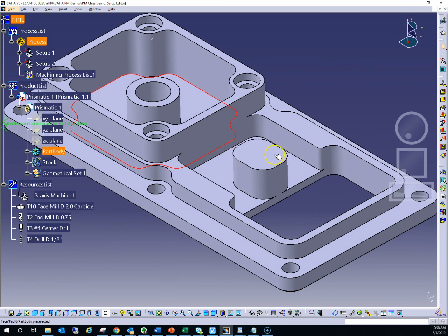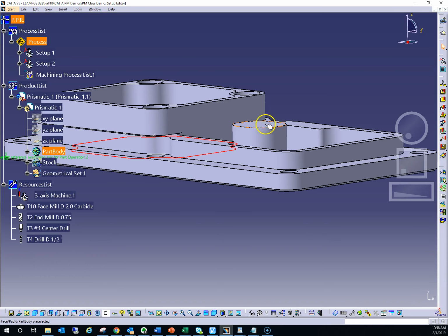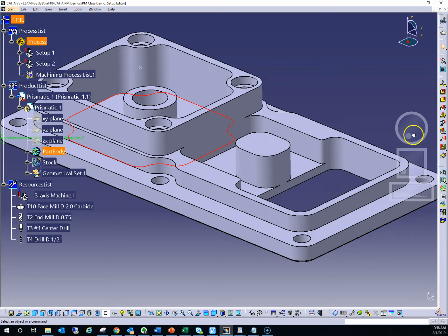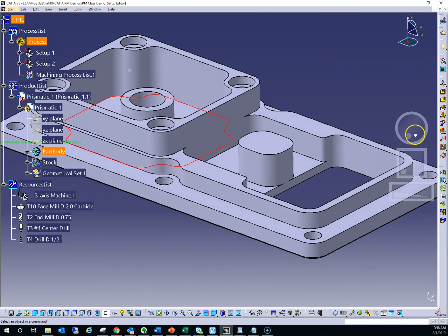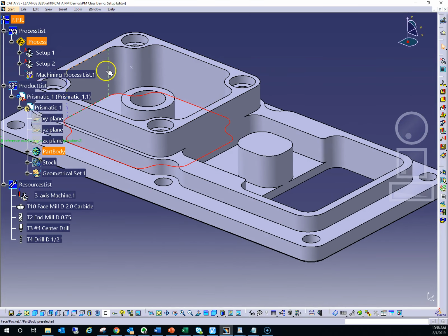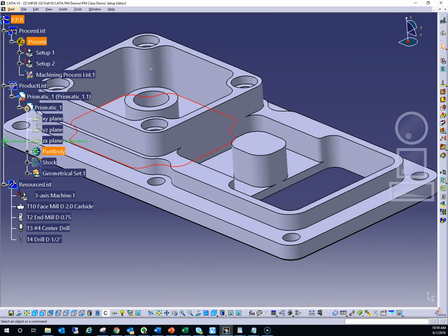So in this case, if we consider this a bottom surface, all this material on top of it is actually a pocket in some sense, except that it's an open pocket. This over here is a closed pocket because there are no open walls. But on this region here, with this as the bottom surface, we actually have 3 open sides in which to generate that pocket. So if we look at that, what would that look like?